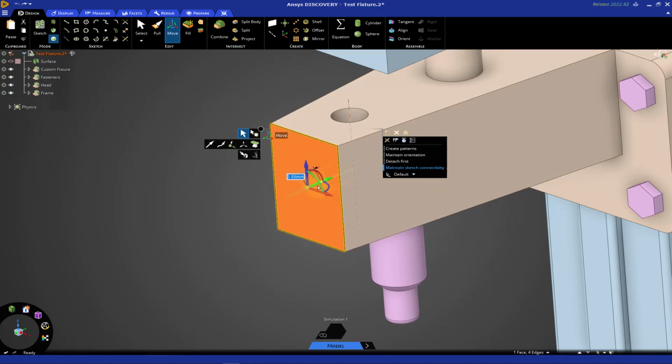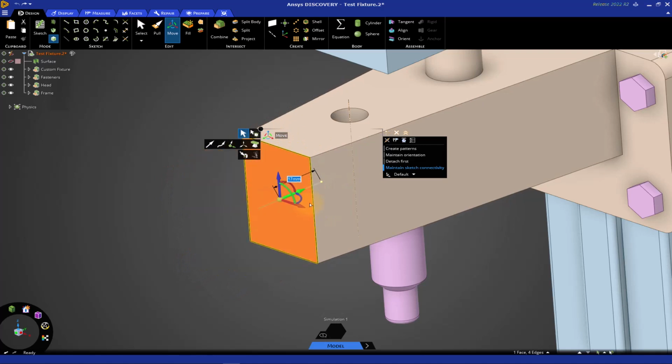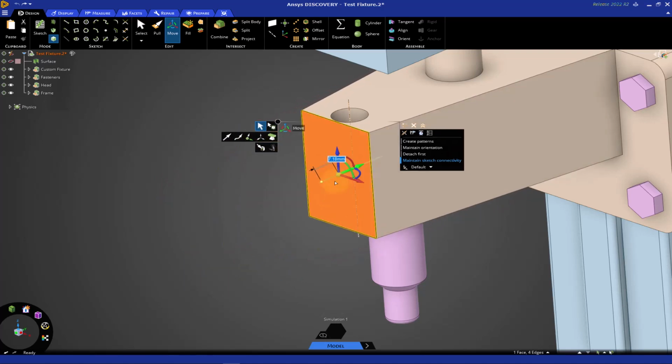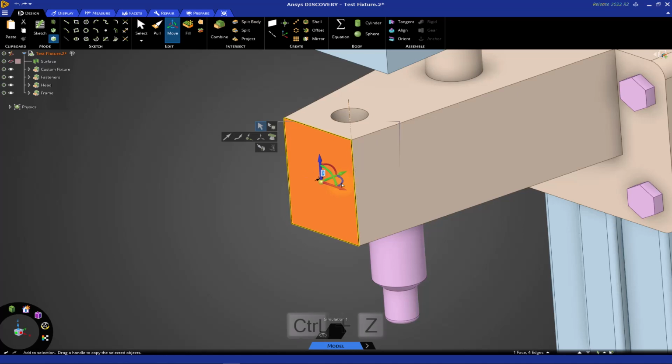There is a difference there. You'll notice that as I do this, the face is now staying the same size, similar to Pull, but with Pull, it created new walls. Now you'll actually see that as I move this, the angle of the faces on the side are changing as I maintain the size of this face. So moving a face with edges is like moving the face without changing the size of it and without creating new walls. Again, similar but different to Pull.